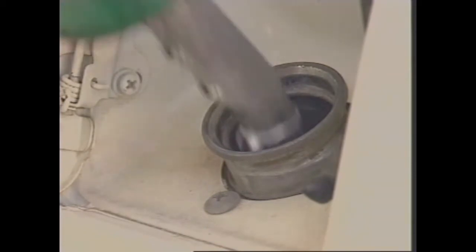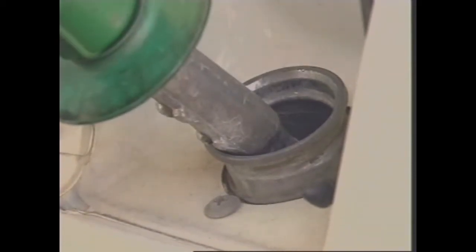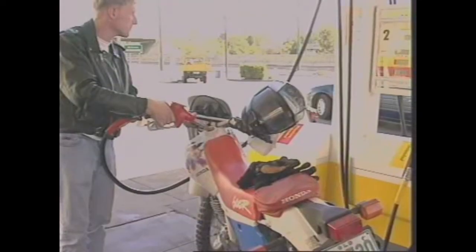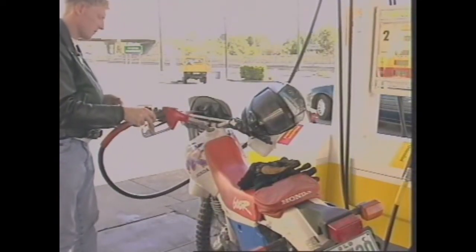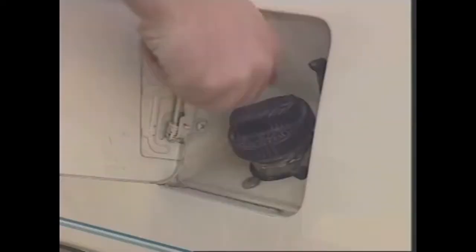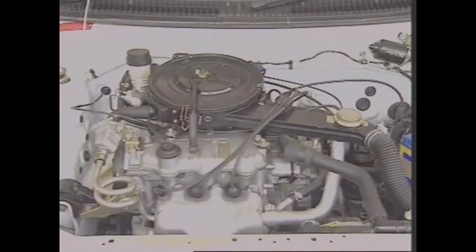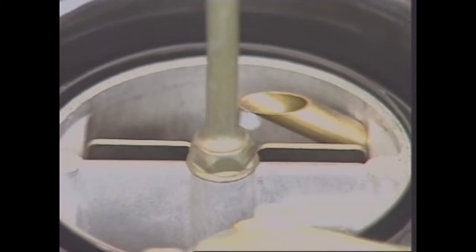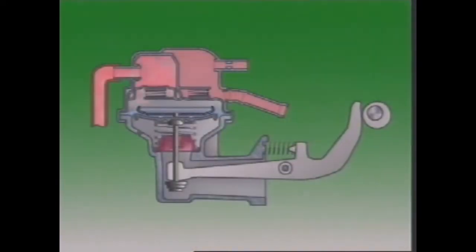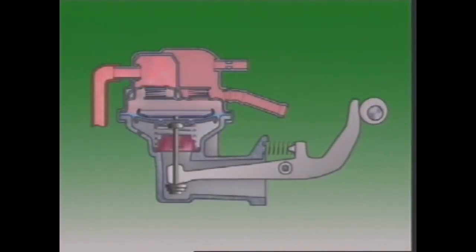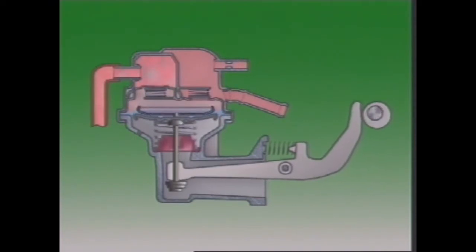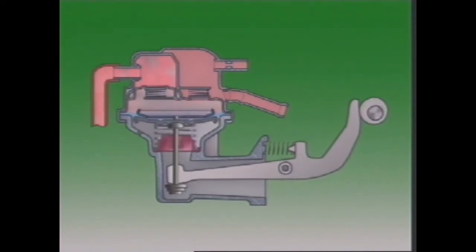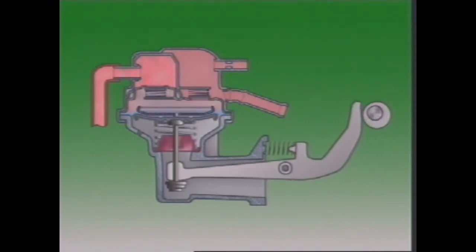Petrol is used in different forms in different engines. It is very volatile, mixing easily with air to form gas or vapour. The more effectively liquid petrol is changed into vapour, the more efficiently it burns in the engine, so high volatility is desirable. And if liquid petrol is heated, it is even more volatile. However, if it vaporizes in the fuel line, bubbles of vapour can block the flow of fuel and stop the engine. This is called vapour lock.